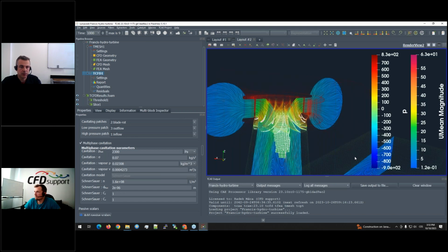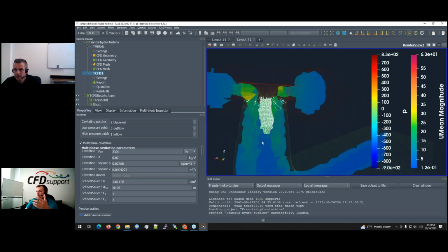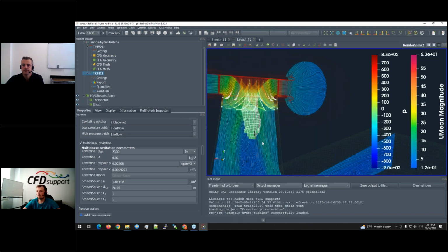So you can go for proper cavitation, but it's of course just in the transient mode. In the steady-state mode, it's just post-processing, exactly. There is no specific detailed model; it just follows the values evaluated with respect to the values of the vapor pressure. We're just comparing the results with the possible cavitation, so it indicates the places where cavitation occurs, but there is no specific model behind it.